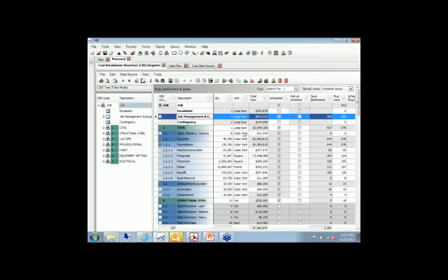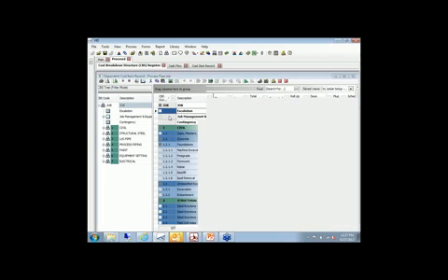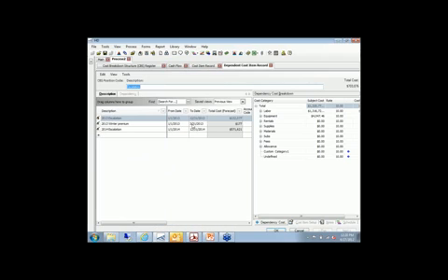Okay, so once we've got that updated now, you can see what's happened here. If you look at our escalation value, it's up to $703,000, and our job management is up to $814,000, right? And that's based on the fact that if we drill into escalation, you're going to see there that now, remember that before we didn't have any escalation happening in 2014, but now that the Primavera schedule tells us, hey, there's work going on in '14, and some escalation values are kicking in.